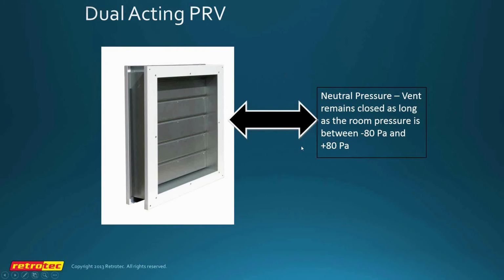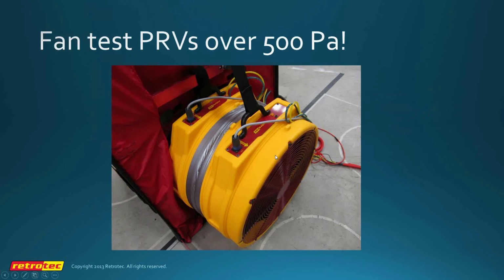And if it doesn't do that, then there is probably something wrong with the vent or the venting path, which could be the other problem. So the vent might work fine. It might be attached to a duct that's not allowing for flow, or might be blocked in some other way. So a key part of the process now is to measure the enclosure leakage for hold time and also to measure the pressure relief venting path, which assures that you actually have the venting that you know you have. This is a new fan configuration that we evolved, which is called our contra fan. It's 2 of our fans connected together, but they're not running in the same direction.